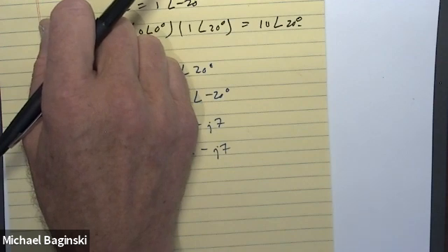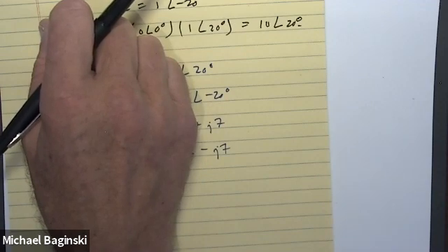All right, so how you reduce the angular difference between voltage and current is by adding a capacitor, almost always in parallel. Now, the reason I say almost always is because there will be a problem that makes sure that you know what you're doing, where they give you something that, instead of having a lagging current, has a leading current. You've had one problem like that already, all right? That is basically fiction. All right, maybe there's something out there that does that. I've never encountered it, and I don't know what it is.